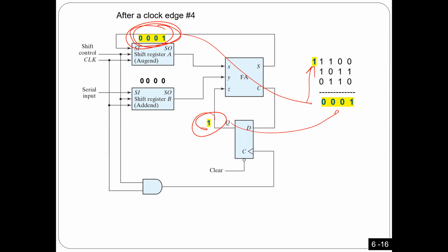Again, I just want to give you some idea, just in case in the future you see something like, I'm going to do this operation in parallel, or I want to do this operation in serial. This is also an application for a shift register. How can you use a shift register? The idea is that every shift, I'm going to get one bit. I'm using here only 1 full adder, even if you're adding 100 bits plus 100 bits, because it's still 1 full adder. This is the interesting part, but it's slow, right?